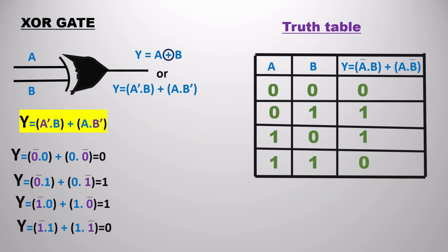To verify the truth table, we put 0 0, 0 1, 1 0 and 1 1 into the main equation we have derived, and the circuit also we have derived. This symbol is the shortcut symbol for the above circuit that we derived from the equation. If you observe, I have put all these things: 0 0, 0 1, 1 0 and 1 1. We obtain 0, 1, 1 and 0. So put those outputs in the table. Hence verified by putting in the expression also.